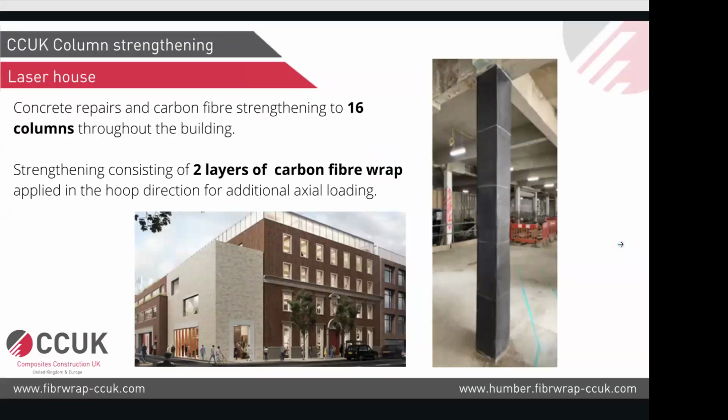Here's a project example for that, another London project. So in this case as well, the same theme here. They had an existing building. They added one more story on top of it. The columns in the basement got overstressed and needed strengthening. But these are not reinforced concrete columns. They are steel columns encased in concrete.